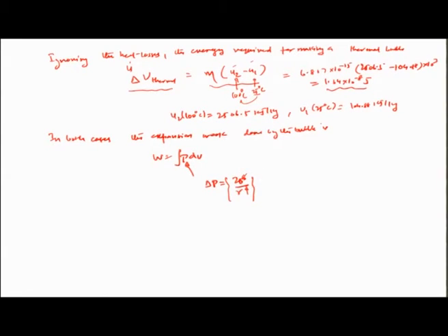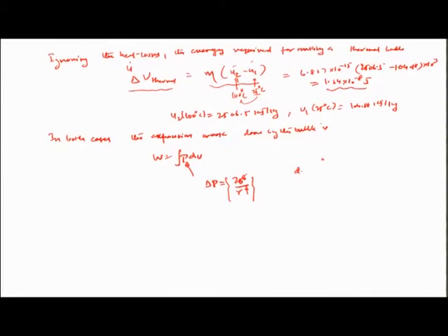So, in this particular problem, if we assume the bubble to nucleate as a spherical bubble and formulate generally a zero contact angle overall occupancy within the channel, the spherical volume being 4 by 3 pi r cube, the dV in that particular case would be 4 pi r square dr. Okay.